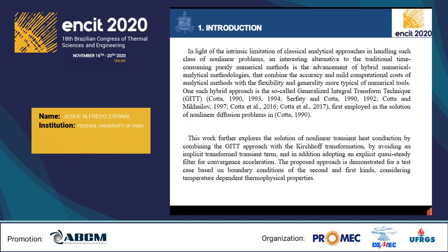In addition, nonlinear heat conduction problems can be reformulated through the well-known Kirchhoff transformation, where the nonlinearity associated with the temperature-dependent thermal conductivity is removed from the governing equation, and collapses into the nonlinear thermal capacitance, explicitly introducing the nonlinear thermal diffusivity in the new formulation.